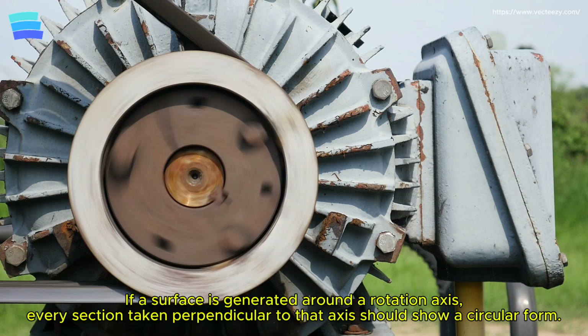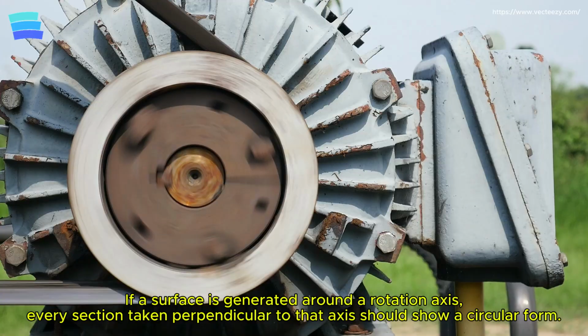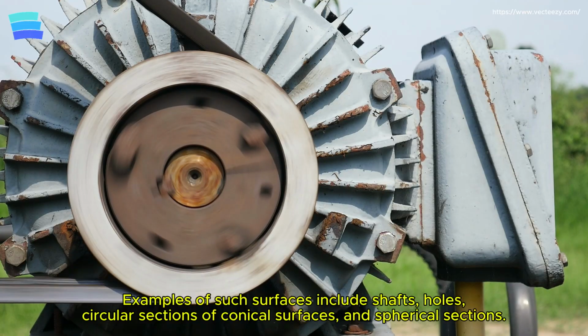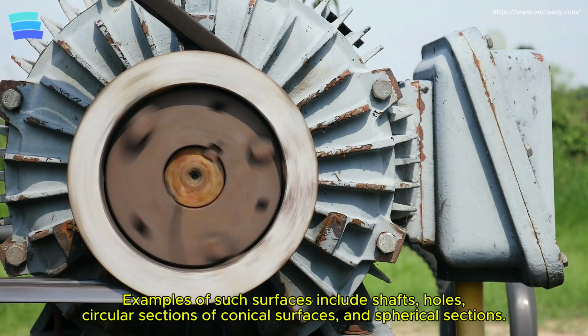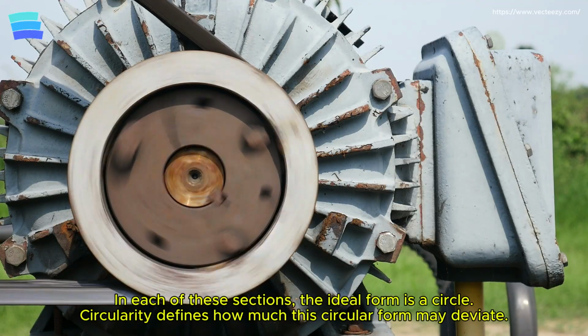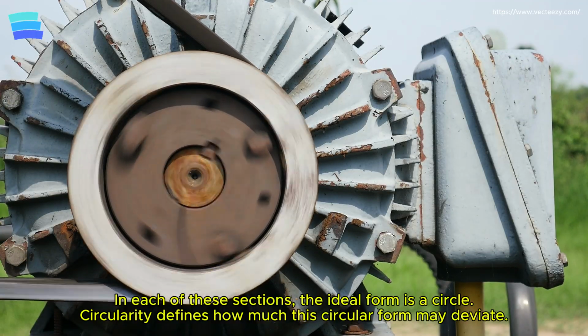If a surface is generated around a rotation axis, every section taken perpendicular to that axis should show a circular form. Examples of such surfaces include shafts, holes, circular sections of conical surfaces, equatorial or transverse circular sections of spherical surfaces. In each of these sections, the ideal form is a circle. Circularity defines how much this circular form is allowed to deviate.